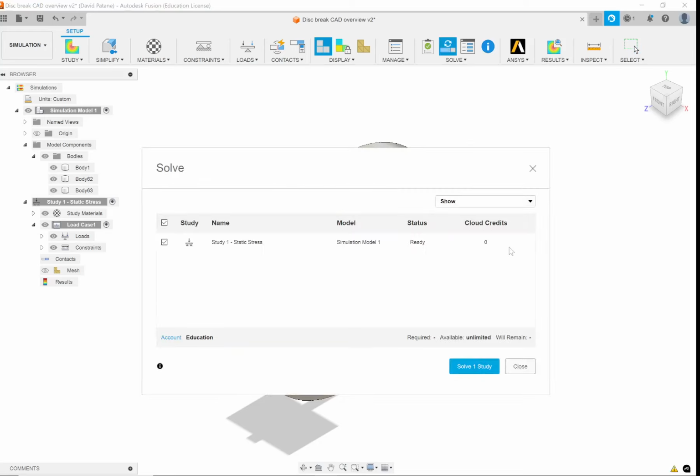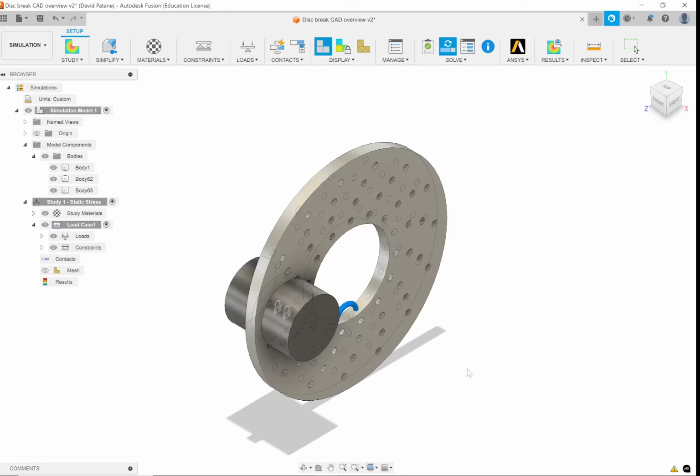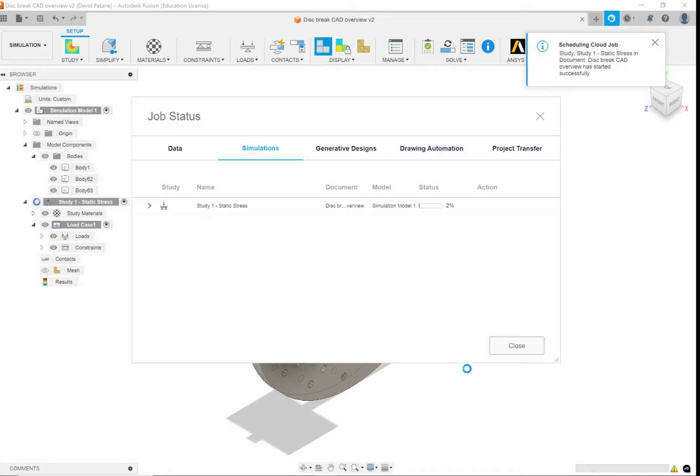So what we're doing here is seeing how this disc brake is affected if I twist it 100 Newton meters. And then I can run this study. The computer's analyzing, doing all these stress calculations. We've done some basic understanding of stress and strain with our calculation of, what is it, stress equals force over area. It's doing these on a very tiny level.